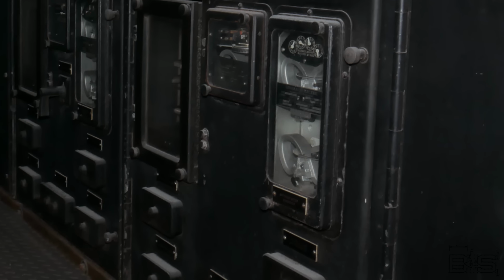We have to make sure that the voltages match, the frequencies match, and that the voltages rise and fall at the exact same instant as our other generator. Otherwise, we will trip the reverse current device, which will forcibly open the circuit breaker.